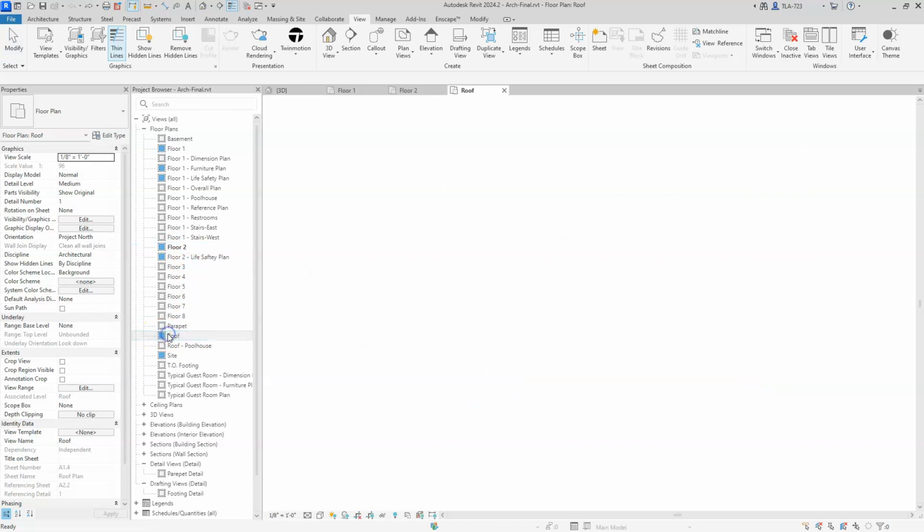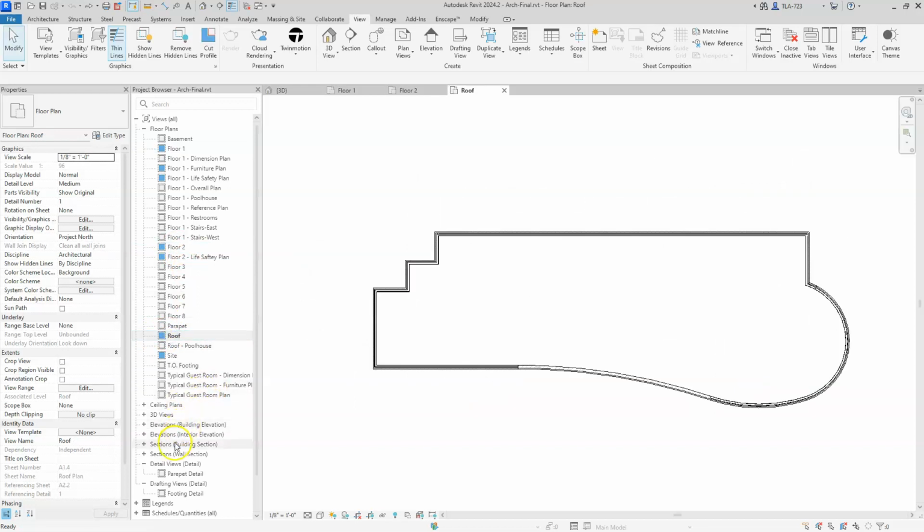We can, and we often find that as we're working on a project, we open a lot of different views because modeling requires us to look at our model from different directions, right? To make sure that we have things right. It's very common to have to switch between views very frequently when we're modeling. And it's good practice to do that because when we draw something or when we create something in Revit, we don't know what it looks like from the other directions, right? The wall could be inside out, it could be not tall enough, it could be too low into the ground, things like that, that you really can't tell by looking at a plan view. So sometimes we have to switch to a section view or an elevation view to really see what's going on.